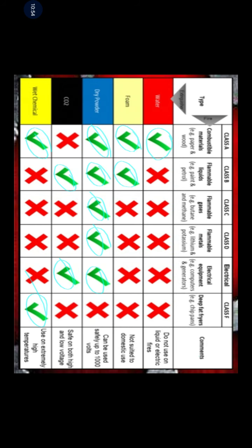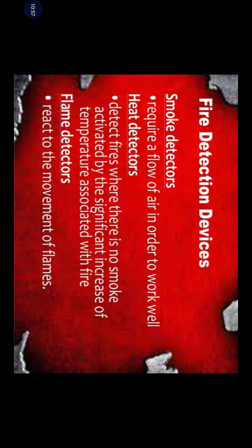The next one, fire detection devices: smoke detectors, heat detectors. Smoke detectors require a flow of air in order to work well. Heat detectors detect fires where there is no smoke, activated by the significant increase of temperature associated with the fire. Flame detectors react to the movement of flames. Smoke detectors require a flow of air in order to work well.